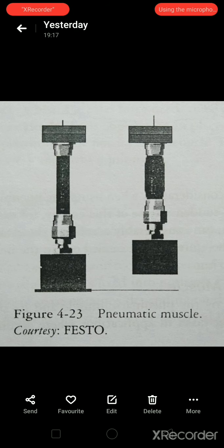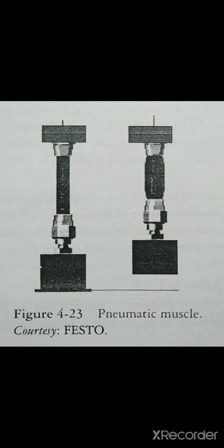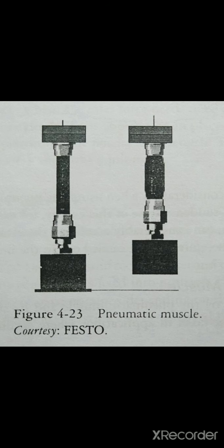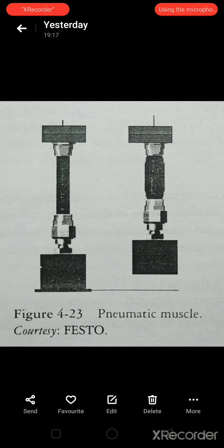The advantages are, first, development of up to 10 times higher initial force compared to a conventional piston cylinder with an identical diameter. Second, highly dynamic operation and high acceleration are possible. Third, no stick-slip characteristic, as there is no piston used in the muscle. Intermediate positions can be set easily by regulating pressure, and it has a low cost.